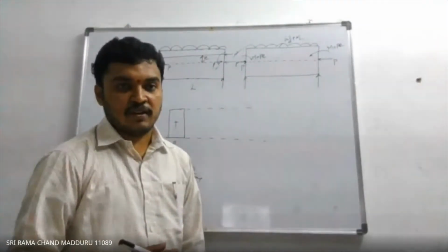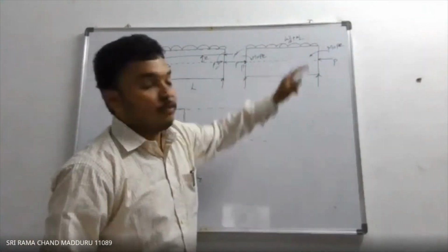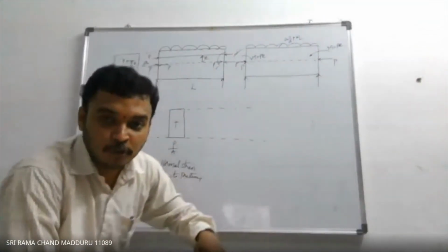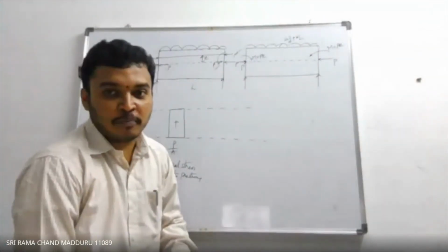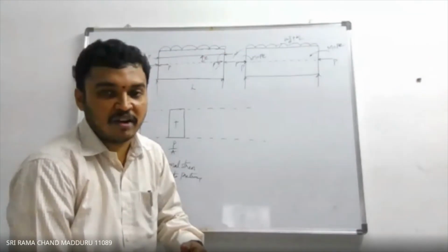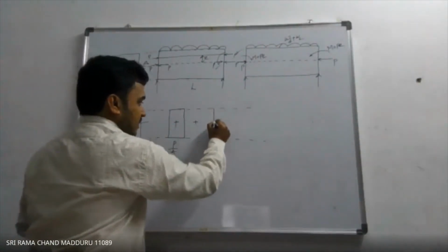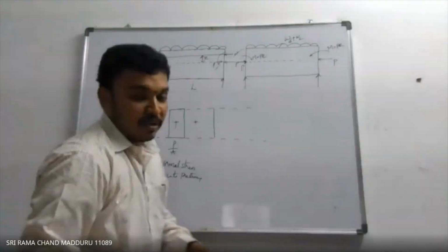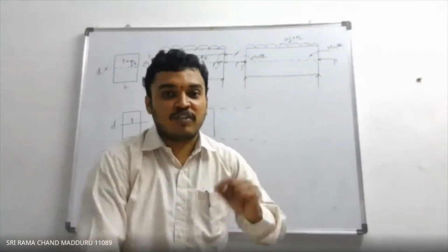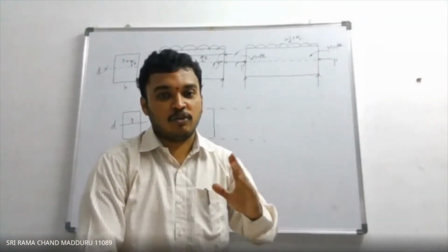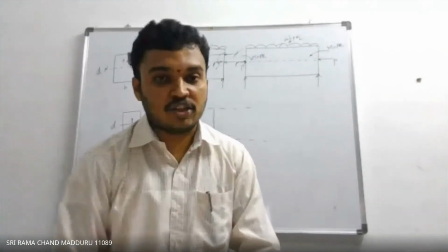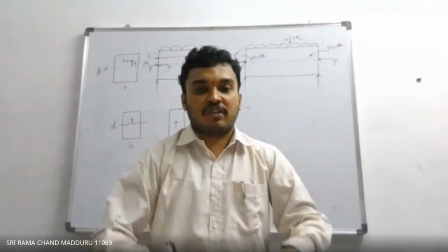That is the first one. Second, we have to write bending stress due to pre-stressing. Which fiber will be under tension and which under compression? We need to understand the direction of the moment due to pre-stressing.